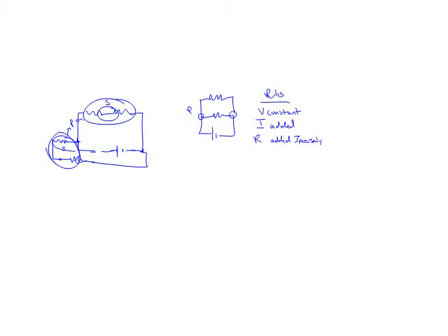And you're like, okay, what is that? It means that for each resistor, you're going to do 1 over that resistor, add it to the next 1 over that next resistor, and it should equal 1 over the total resistance. So a lot of times you'll end up with some sort of number here, and a lot of people get stuck. Just flip-flop the bottom and the top.